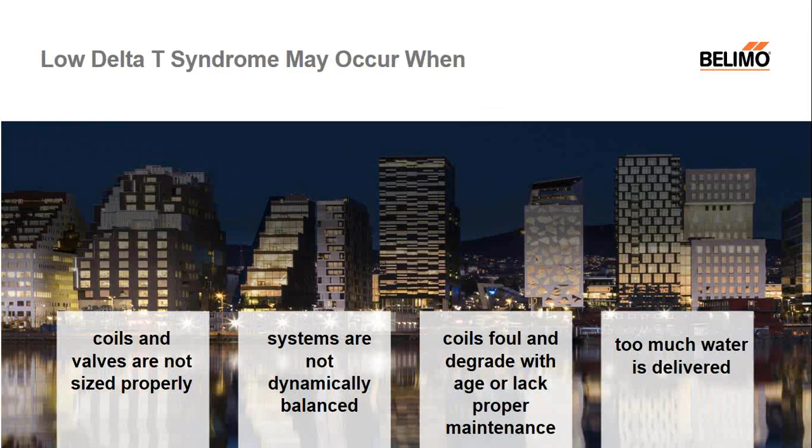Systems are not dynamically balanced. Here, this is related to pressure-dependent valves as well, so not using pressure-independent valves. These pressure-dependent valves are at the mercy of pressure fluctuations within the system and are going to have a negative effect on control based on those fluctuations in pressure.